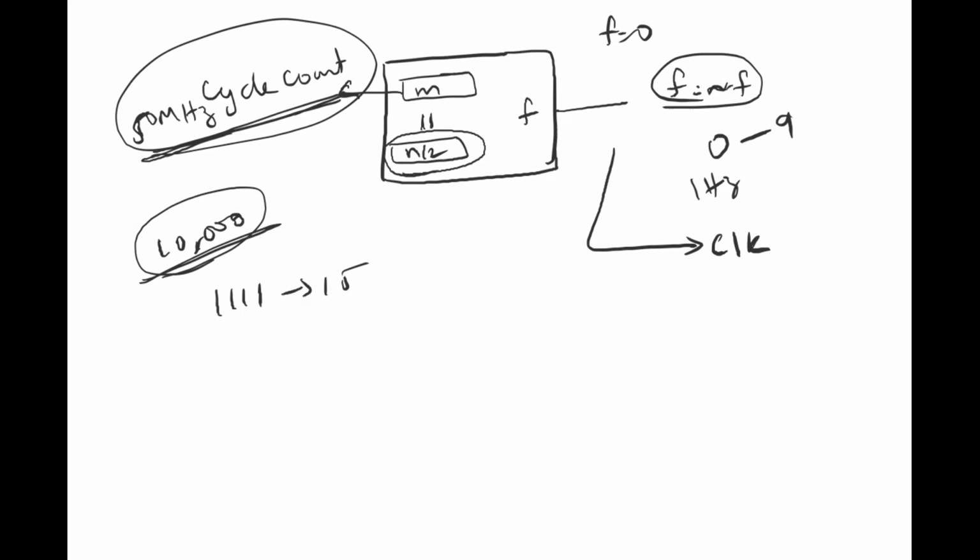So yeah, I had a quick question. Sure. On this, how do we get the default clock in Verilog? Oh, so in your Verilog you just give the input to be a 1-bit clock named clock, right? But when you actually implement it on the board, that's when you have to go through your user manual. There should be a clock pin inside it, so you can connect this particular clock input to that pin when you put it on the board.